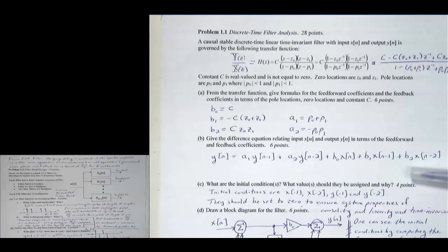We really do use this in practice. This is a very well used technique. To build a spectrum analyzer out of this, all I need is to do an absolute value of every output. I just put an absolute value or absolute value squared. I now have computation of power in each band. I have a spectrum analyzer, uniformly spaced.